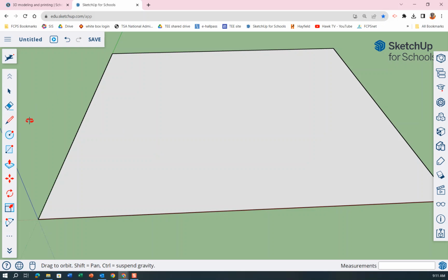So I'm going to start off with a rectangle. I'm going to go down here. Again, I'm going to start at the origin and just start moving it. And I type in 90, comma, 30, enter. Those are the keys I press. Notice I do not go down in the dimensions field. You never want to go down there. It just causes trouble. So here's my keychain, okay?